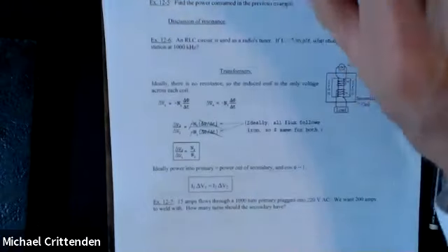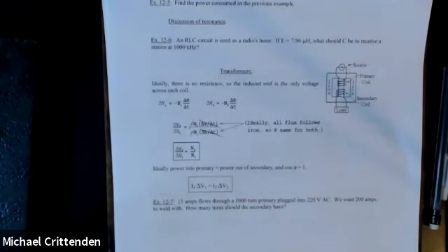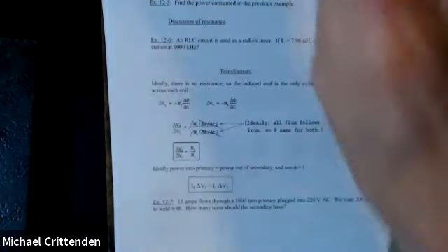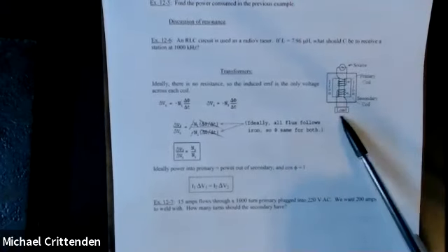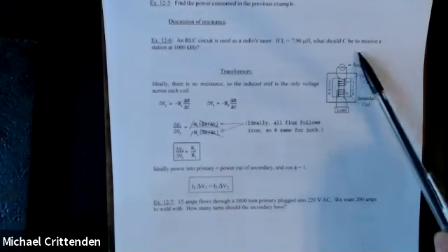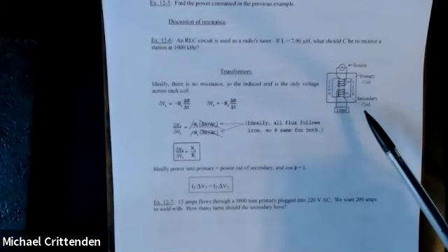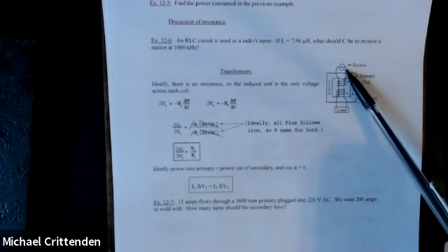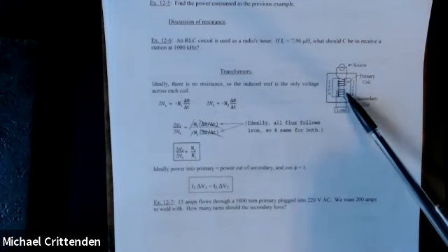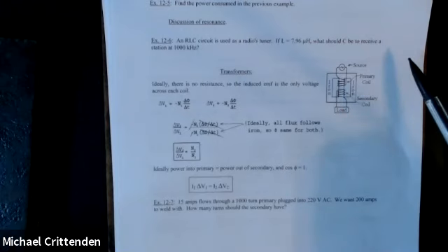That's what I get for trying to do math in my head. 120 divided by 6. Yeah, 20. I did that right. 20 to 1 ratio with the voltages, 20 to 1 ratio with the number of loops, okay? So maybe you've got, I don't know, 1,000 loops on this coil and you got 50 loops on that one or something like that.